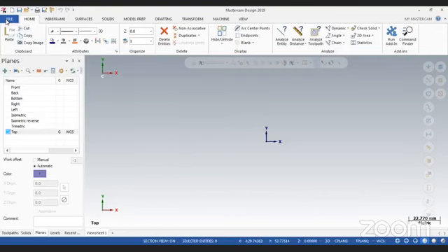So here is the main screen of Mastercam. We can see the user interface is like any CAD software, in which we can have WCS, World Coordinate System. Apart from it, Mastercam has some toolpaths, some toolings, and details regarding simulation and verification. So first of all, we need to generate a CAD model through a CAD software.